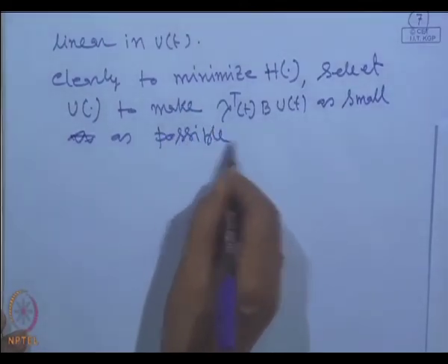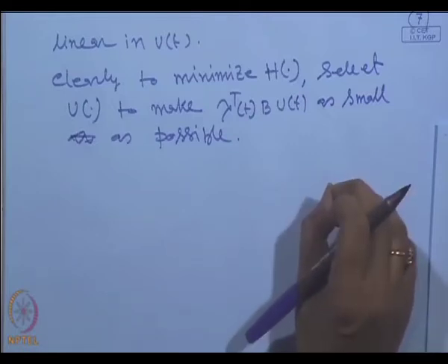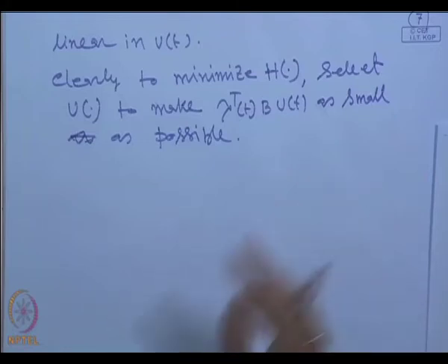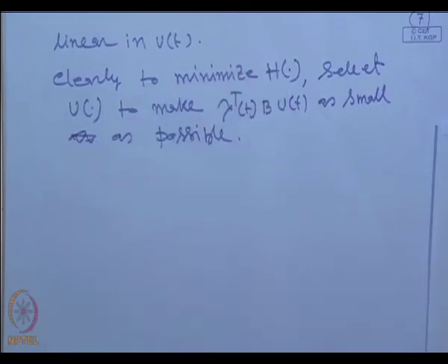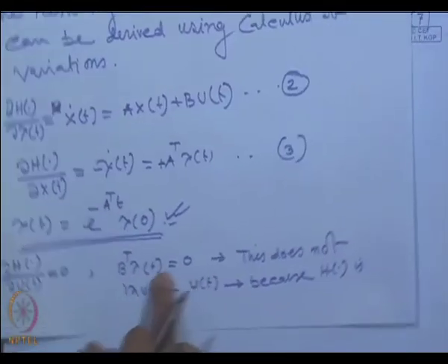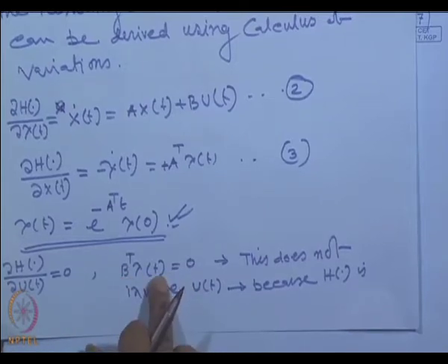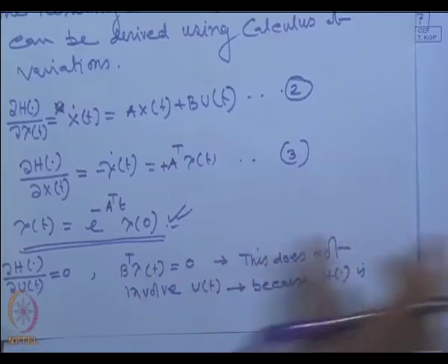So, that is our requirement. This is called the Pontryagin minimum principle. We have to minimize H, but we cannot minimize H by selecting u, because there is no u term involved; the Hamiltonian function is a linear function, not a quadratic or a nonlinear function.